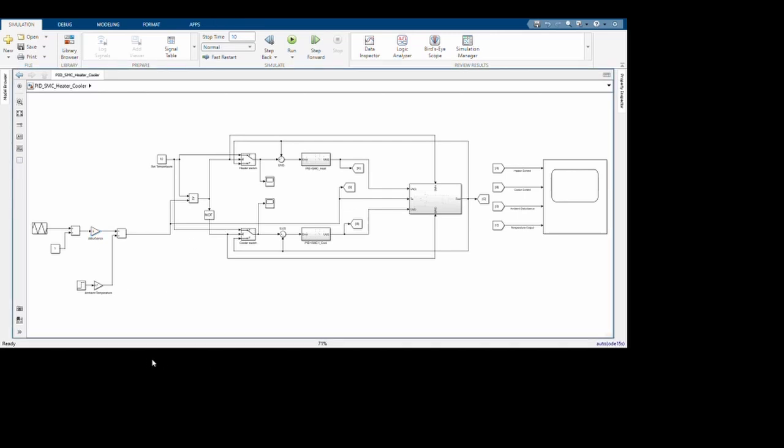And our actual ambient temperature is around 27 degrees centigrade, but obviously real world temperatures fluctuate in the micro degree Celsius sense. So that's how it happens. Now our set temperature is compared with our ambient temperature, and if our set temperature is higher than our ambient temperature, then this relational operator block will output a value 1, which will turn on this heater switch. When it turns on this heater switch, it will turn on our PID plus SMC heating control block.